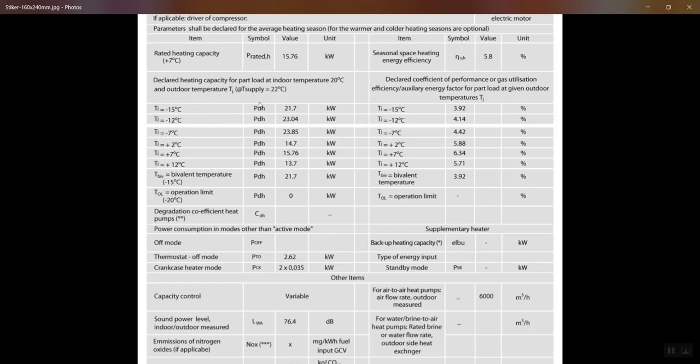To achieve correct values inside this table, we decided that each of our calculations is based on a supply temperature of 22 degrees. So basically, for each of the ambient temperatures, with a fixed indoor temperature of 20 degrees and a fixed supply temperature of 22, we have calculated different heating capacities.